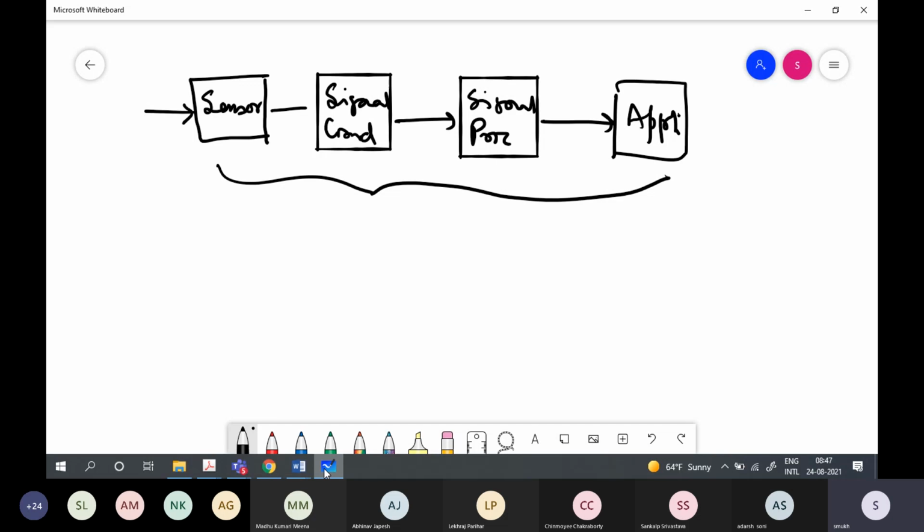We have these high water level alarms in domestic automatic pumps. It is there in my house in Kolkata. The underground tank, which is in the basement of the house, has a submerged pump, and it has a level sensor. Similarly, the overhead tank on the roof also has a level sensor. When the overhead tank level is low, it sends a signal to the system, and the pump starts to pump water from the underground tank to the roof tank.